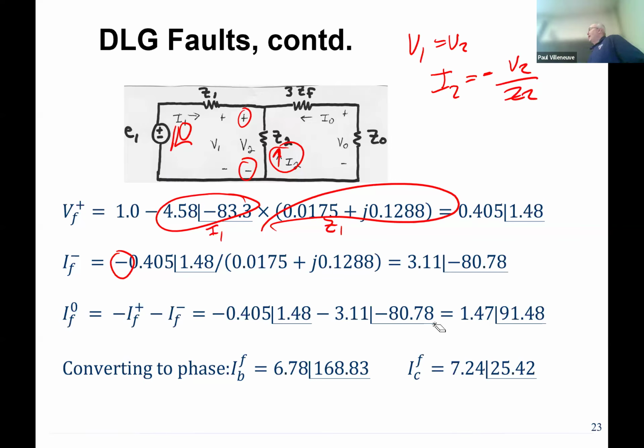But yeah, you could check them all. I usually only check three-phase fault and single line to ground, because it's so atypical to see those other two have a greater impact. And usually you're trying to coordinate the worst one, because anything beyond that is going to be slower since it has lower current values. So you worry less and less about the line to line and double line to ground. It's just going to take longer to trip, but that's okay, because you have less energy to cause problems. I'm not saying don't trip, but you don't have to take as long. So you might want to check those to make sure, if you have a line-to-line fault, is there enough fault current to actually get your system to detect it and trip? That would be a kind of cautionary tale.